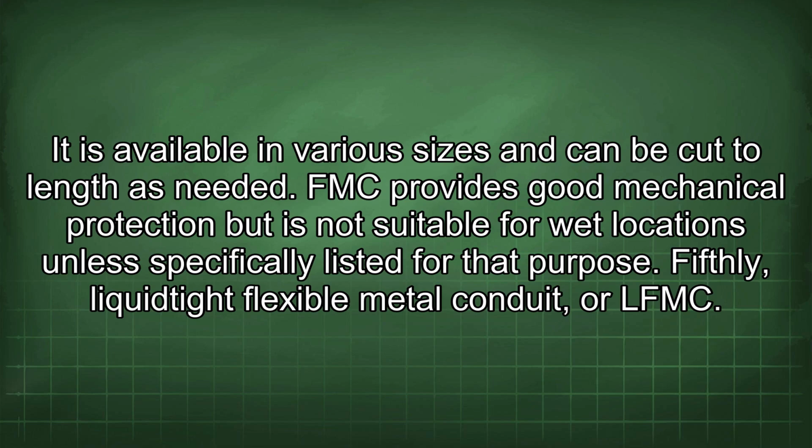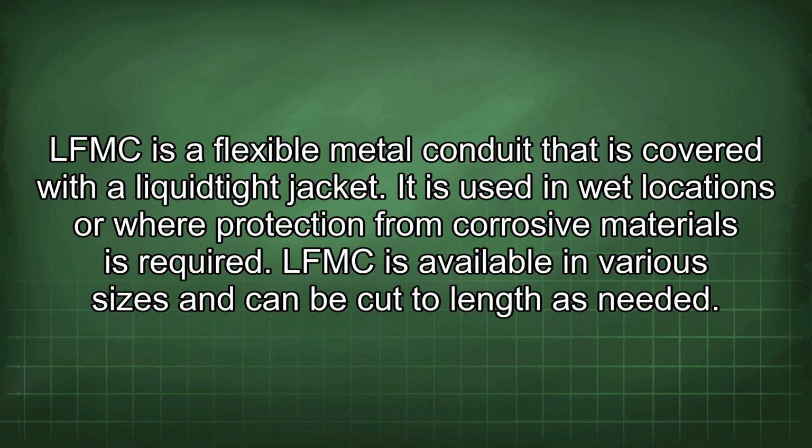Fifthly, liquid-tight flexible metal conduit, or LFMC. LFMC is a flexible metal conduit that is covered with a liquid-tight jacket. It is used in wet locations or where protection from corrosive materials is required. LFMC is available in various sizes and can be cut to length as needed.